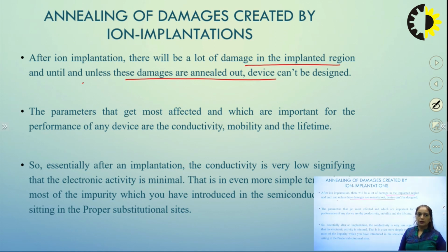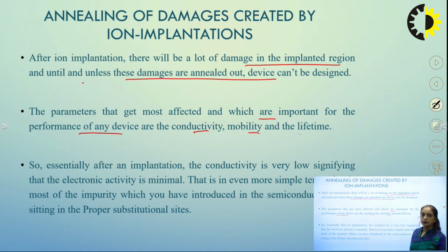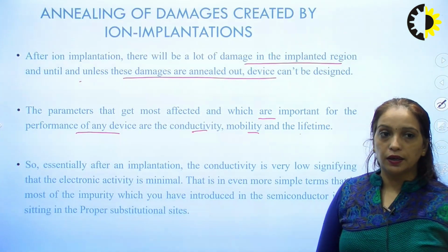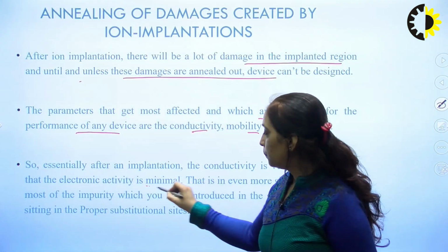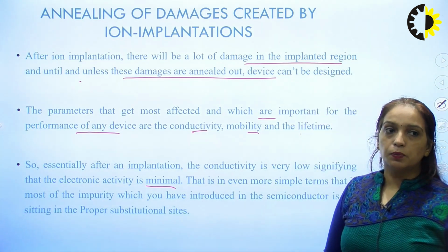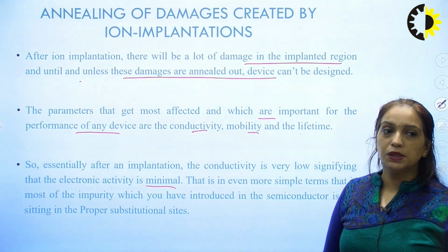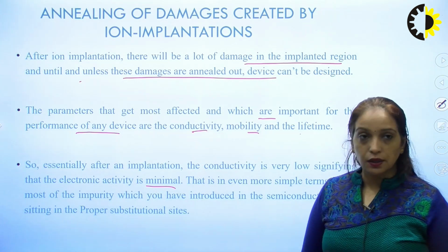The parameters that get most affected, which are important for the performance of any device, are the conductivity, mobility and lifetime. After an ion implantation, the conductivity is very low, which signifies that the electronic activity will be minimal, right? In simple terms, most of the impurities you have introduced in the semiconductor will not be sitting in the proper substitutional sites.